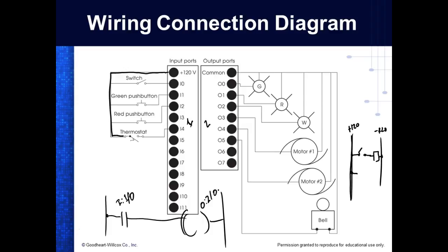So when I hit this button, there's the truth. That is the symbol that says I have a switch hooked up there. So that's what I'm trying to get across. When you draw your connections to your modules, you're supposed to use the industry standard for these different devices. So what's the top one? Normally open, single pole, single throw. Anybody know what that means?